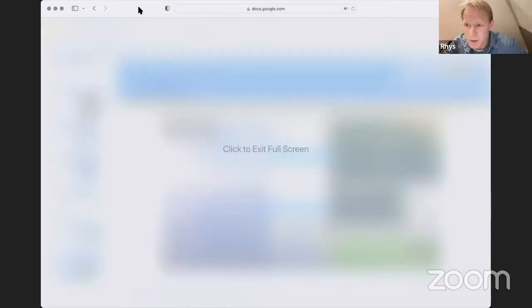Right. Yeah. So there's two approaches, I think. The ROS GZ layer has a mapping of the camera sensors through into the standard ROS image messages. So you could use that, or you could do it directly with the Python bridge layer that I've provided, or you could write a C++ plugin to do that.